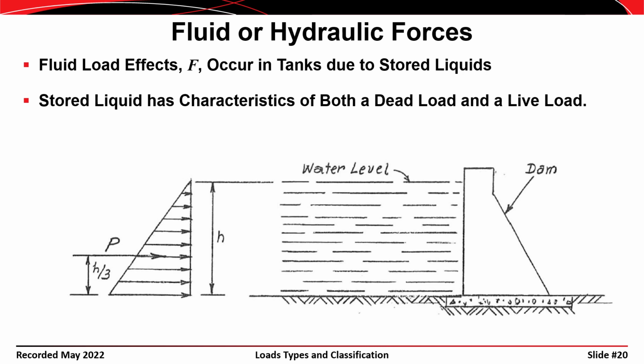Okay, the forces due to most fluids are hydrostatic, meaning that the force increases linearly with the depth of the water. So you can see here that the horizontal component of the force is a function of h. So it creates a triangular loading where the resultant P is at 1/3 of the depth of the water from the base, from the bottom of the tank.